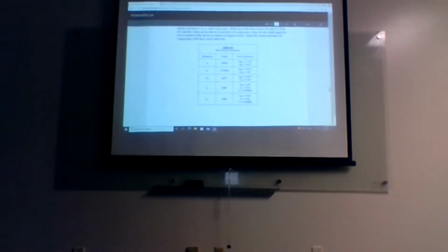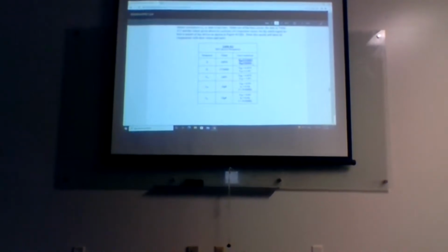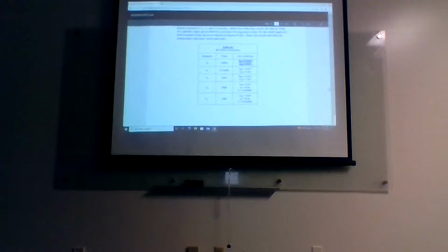Okay, I'm talking about here with IS. If you want to get an accurate value of IS, you just reverse bias the junction and see how much leakage current is getting through it. So that's how they give you a value of IS, and that is the IS value that you would use in your IC equation.